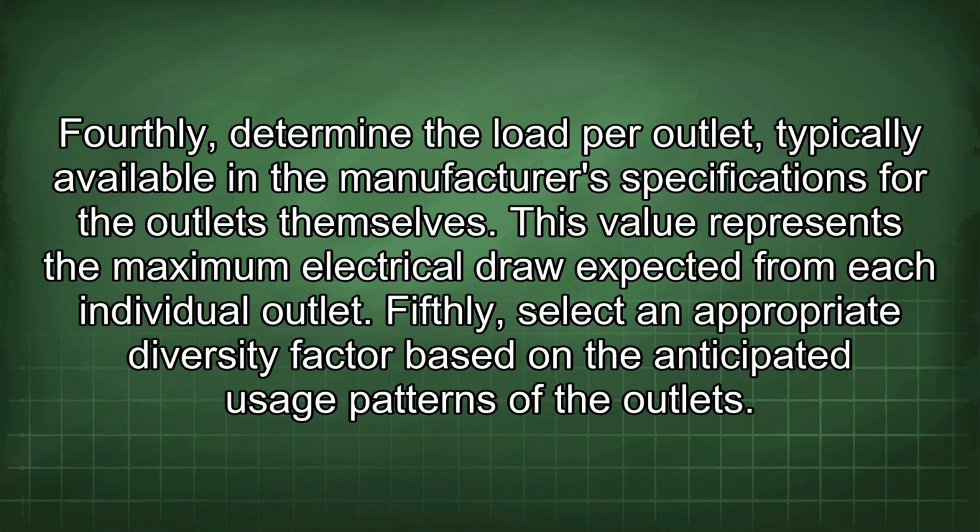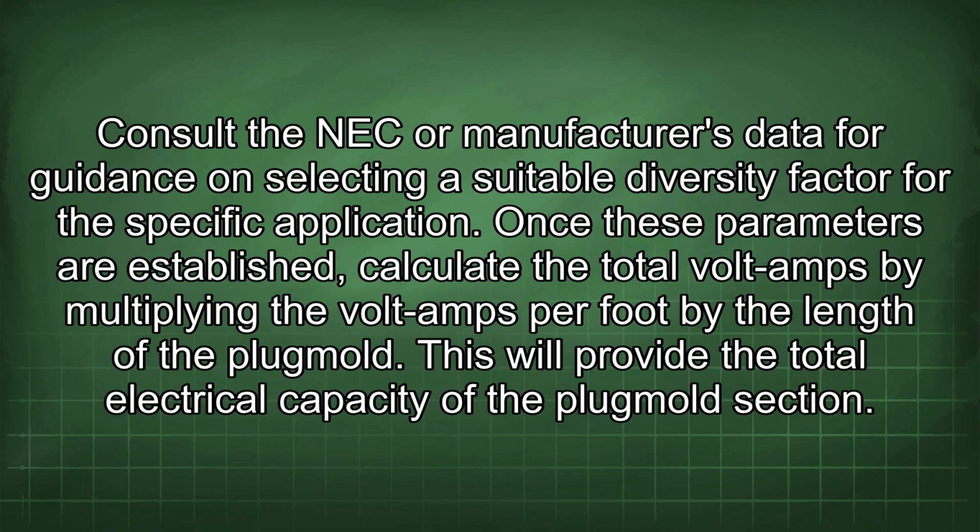Fourthly, determine the load per outlet, typically available in the manufacturer's specifications for the outlets themselves. This value represents the maximum electrical draw expected from each individual outlet. Fifthly, select an appropriate diversity factor based on the anticipated usage patterns of the outlets. Consult the NEC or manufacturer's data for guidance on selecting a suitable diversity factor for the specific application.